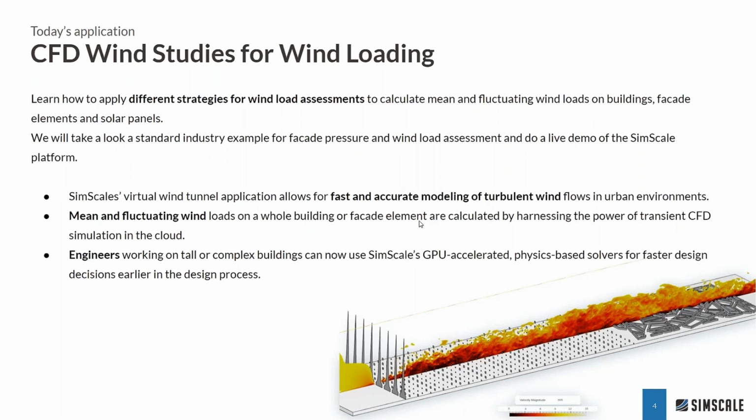So after today's webinar, you should know that with SimScale's virtual wind tunnel application, we can do fast and accurate modeling of turbulent flows in urban environments. We can evaluate the mean and the fluctuating wind loads on the full building or on facade elements by using transient CFD capabilities. And we enable engineers that work on complex buildings to use SimScale's GPU accelerated solvers for faster design decisions and iterations earlier in the design process.